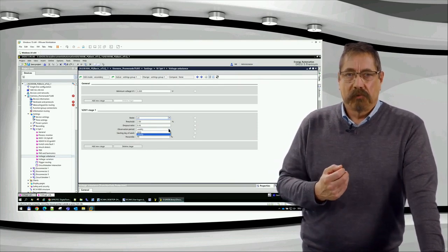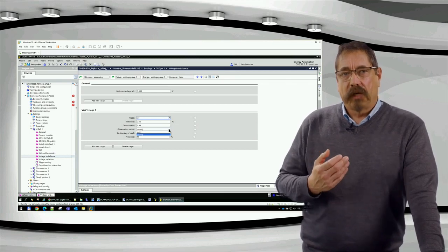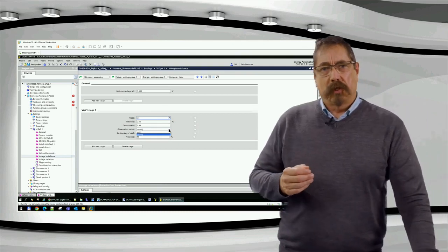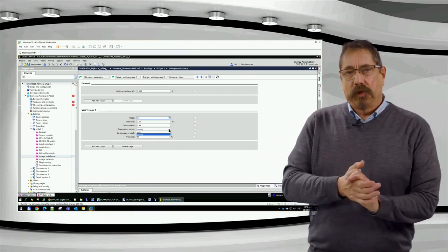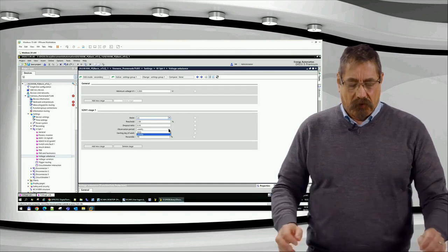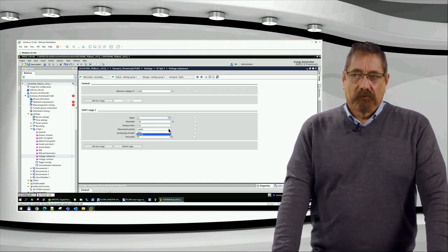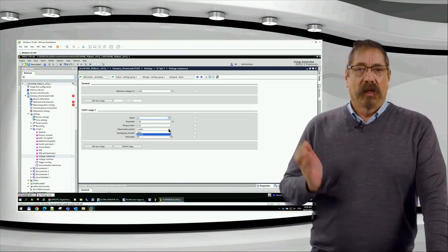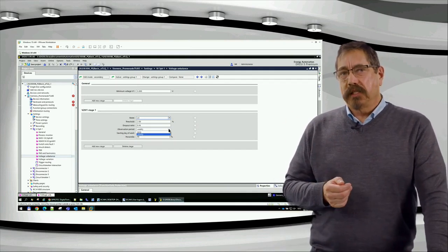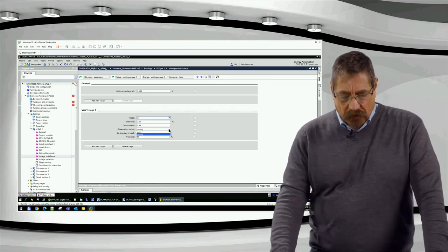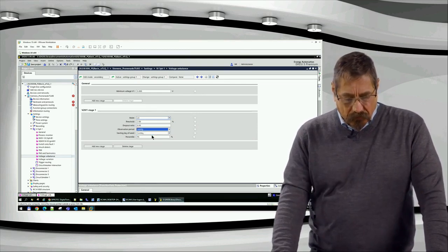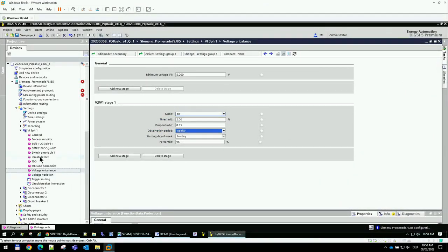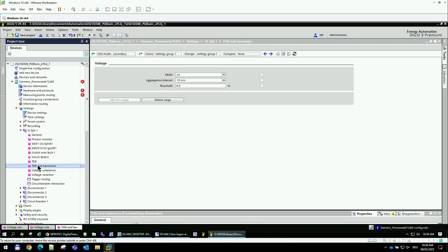You can switch it to day, and then you get evaluation results every day. This means the warning indication will be fired quite a bit earlier. But typically, from the power quality perspective, weekly is a time range which is quite common. We will find this observation week, or monitoring week, or evaluation week also in the grid code EN 50160, for example. Okay, we keep it weekly. And let us now jump to the next one, the total harmonic distortion, or the THD.